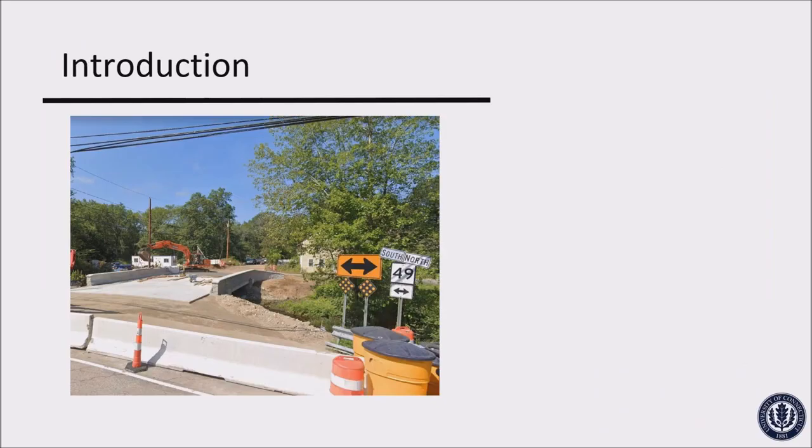In 2018, the Connecticut Department of Transportation identified the bridge across Pendleton Hill Brook as being in need of replacement. For our project, we focus on the replacement phases of the bridge, as well as replacing the abutment designed for the new bridge deck. The replacement phases include rerouting traffic around the bridge, creating a detailed list of replacement stages, and designing a cofferdam and bridge scaffolding to be used during construction.